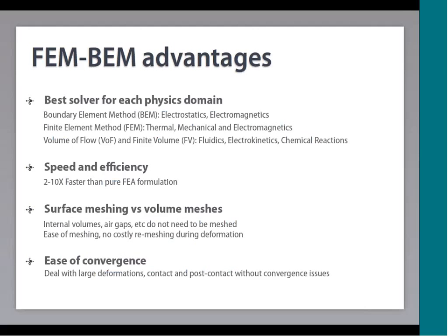The advantage is that it's much more efficient and has much greater ease of convergence, because things like internal air gaps don't need to be meshed, and the air gaps don't need to be remeshed as the simulation is running. It also makes it much easier to deal with issues such as contact and post-contact, which is very important for different types of MEMS devices like RF switches.